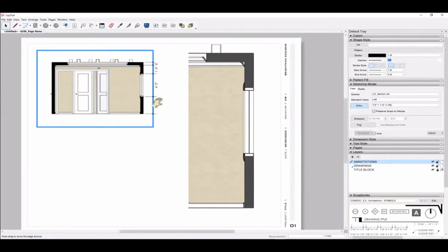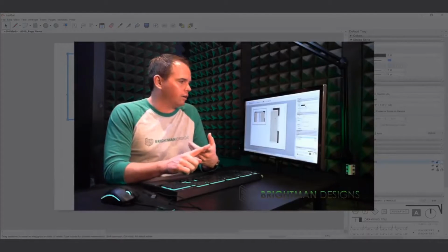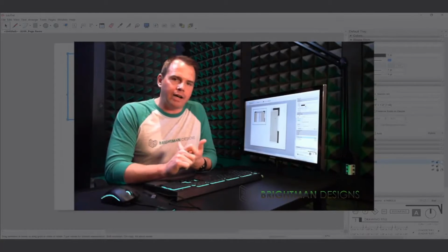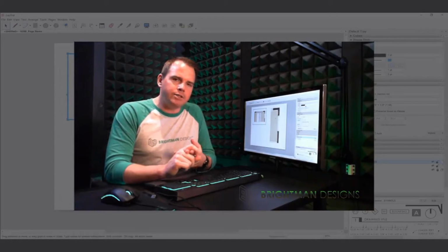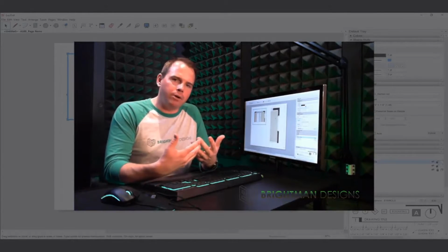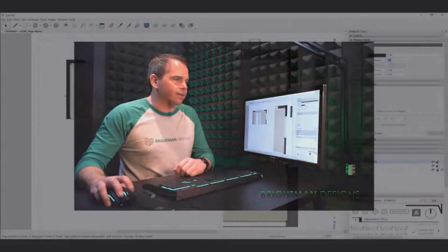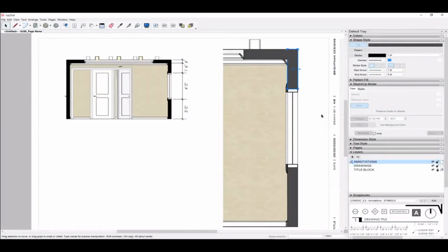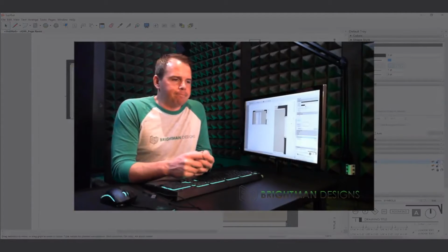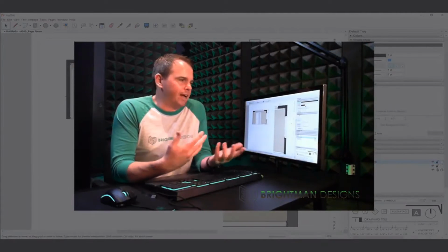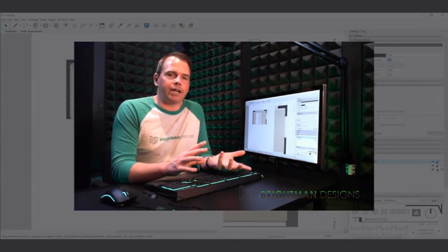So let me just wrap that question up and say that, yes, you can control the color of your line work. That happens in your styles dialog or your styles browser. Typically what I like to do is have that black and white CAD style output. So usually I would just fill in my hatch manually because I think that it happens rather quickly. I save it to the end until I'm buttoning up the drawings. So it just depends. But then the last option, Scalp, is certainly worth checking out.